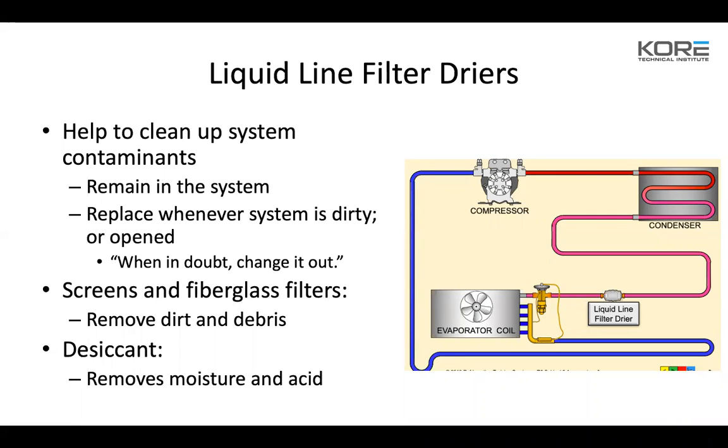This is one thing I want to talk about. We've seen a lot of quotes coming through, and a lot of quotes that I'll kick back won't have a filter dryer in them. So if we're opening up the system for any reason, and this isn't charging, or making a quick adjustment, but if we're going to open up the system and change an expansion valve or change a major component of that system, we always want to add the filter dryer in there and change it at the same time.